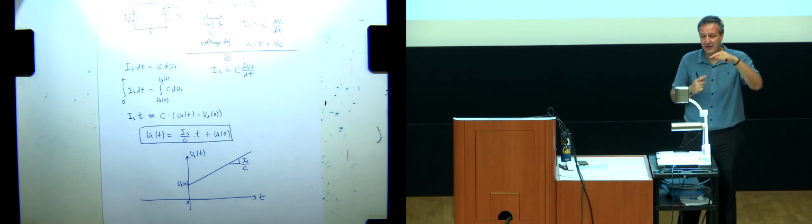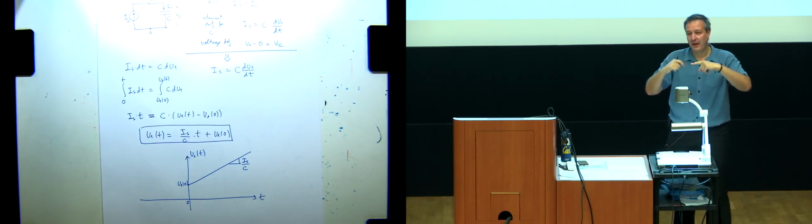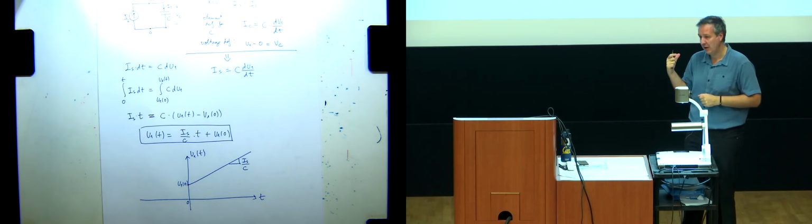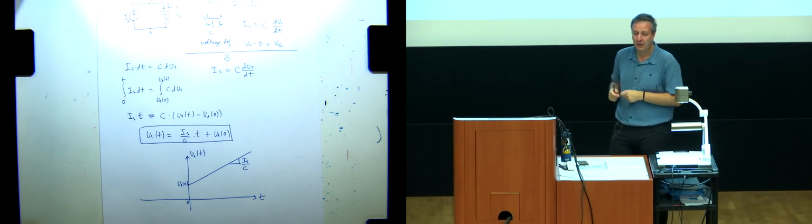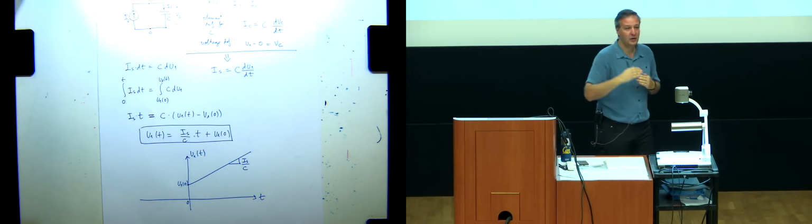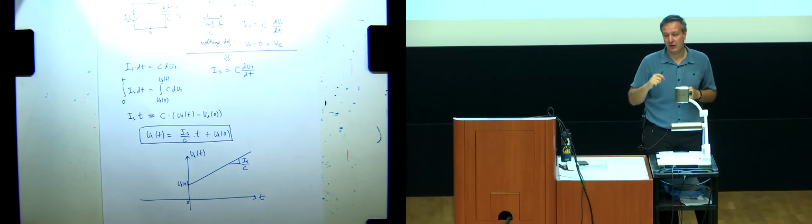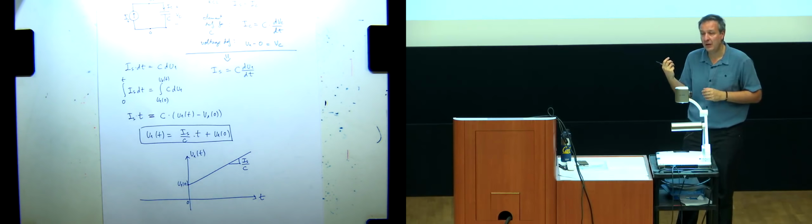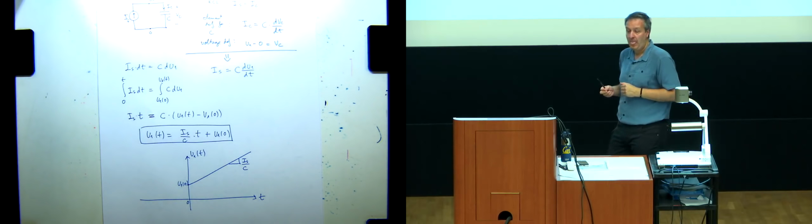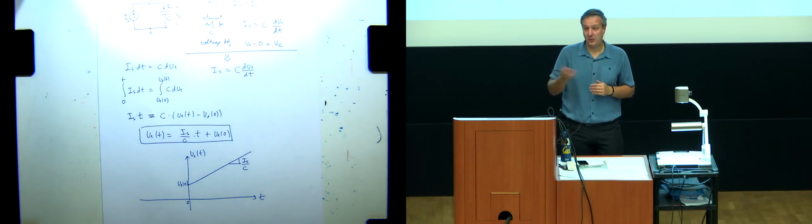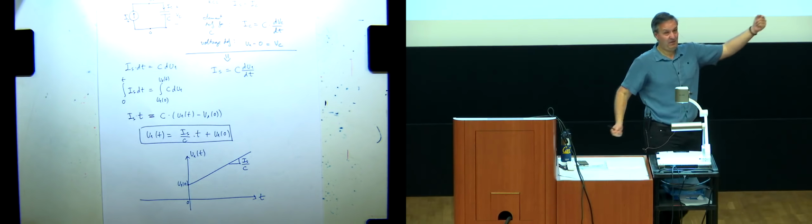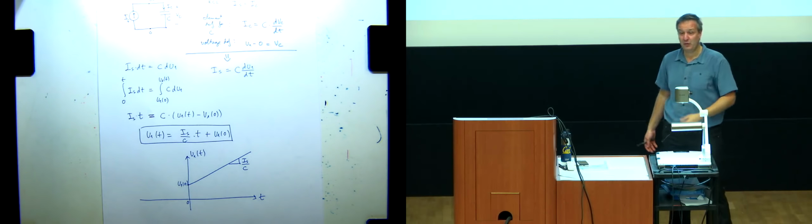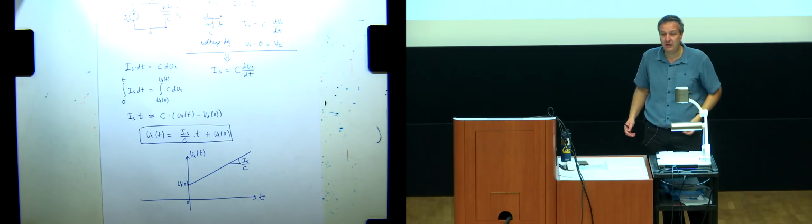And a pop means that there was a breakdown in the capacitor. As we'll see later, capacitor has some insulating material, and just by building the voltage high for a fixed distance, you're actually increasing the size of the electric field, right? And because field is proportional to voltage, if you have a ginormous voltage, you have ginormous field, the field breaks the insulator.